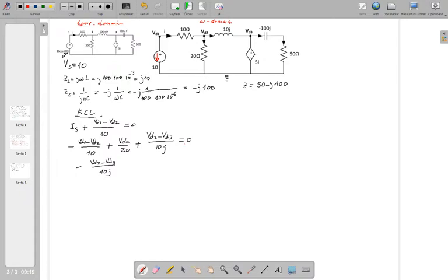So this dependent voltage source's voltage depends on that current. That current is this element's current. So it is a current controlled dependent voltage source. So V of the current controlled dependent voltage source is equal to 5I. That's the definition relation.